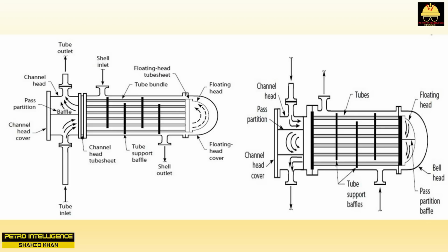Let's say that the tube side of an exchanger is currently operating, after 2 years of service, in a badly fouled state. Its delta P, as measured in the field, is 20 psig. The calculated delta P for clean tubes is 5 psig in a 2-pass configuration, or 40 psig in a 4-pass configuration. After 2 years of operation, I would expect the exchanger in the 4-pass configuration to have a delta P of 50 to 60 psig, rather than 160 psig. Why? Well, because the doubling of the tube side velocity has promoted turbulence, which retards the accumulation of fouling deposits.